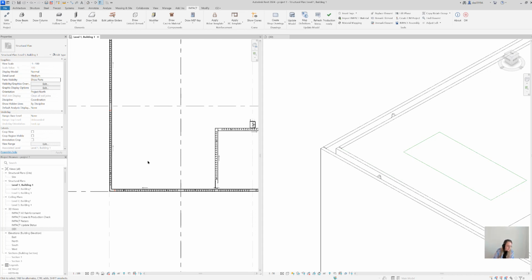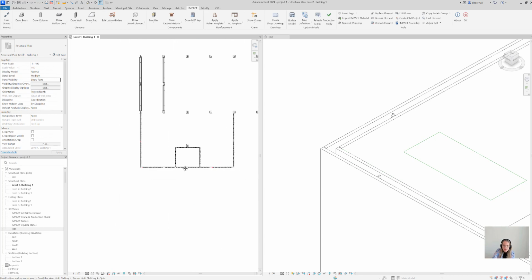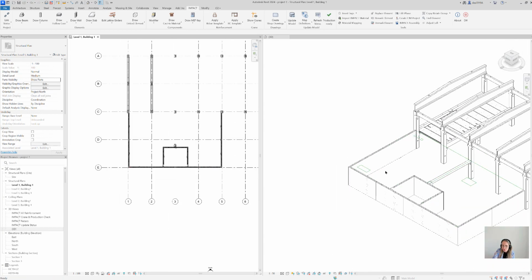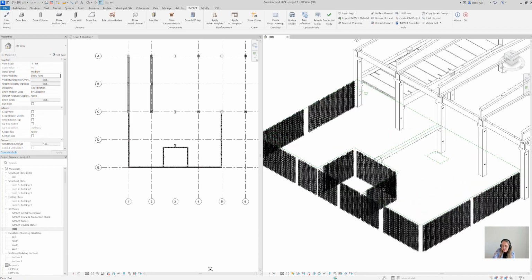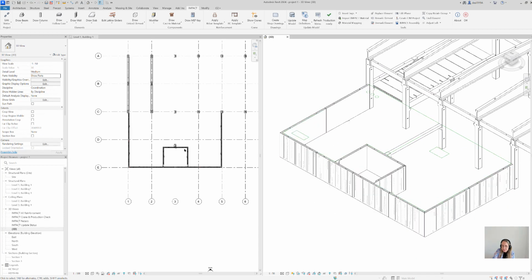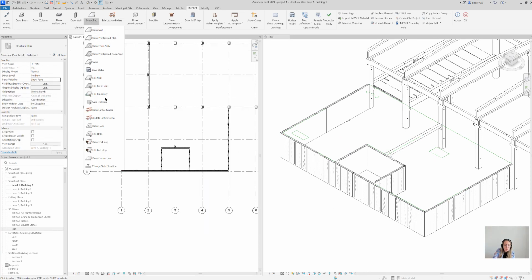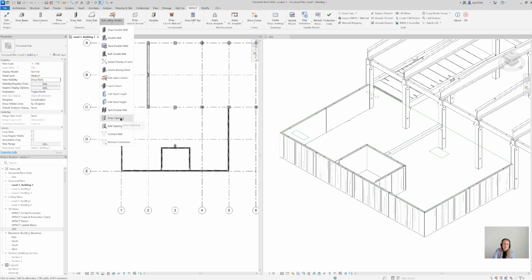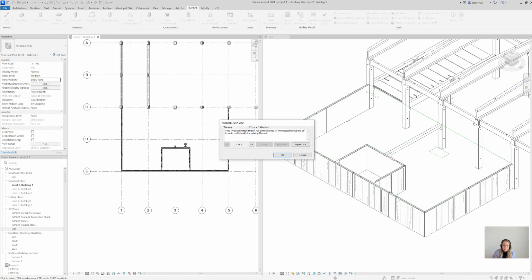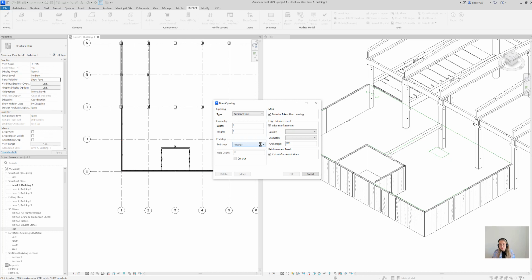Okay, and the last thing we need to do when we talk double walls is some openings. I want to demonstrate the drawing of openings in double wall. And for drawing openings in double walls, we're going to use the customized tool. That's the draw opening in the folding menu for double wall. We strongly advise our users to use the customized functionalities.